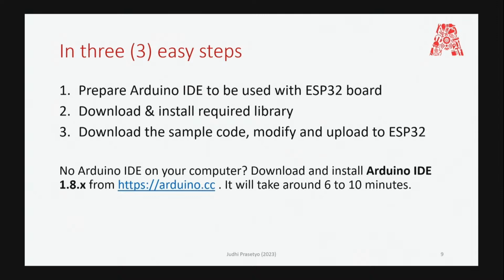You have to let the Arduino know how to use ESP32 board. And then after that, for our purpose, we need to install a certain library. And then I already have a sample code. You can modify and then just upload it. I will explain the code, and then after that you can modify, so every one of you can try, make your own micro key, your own actions.